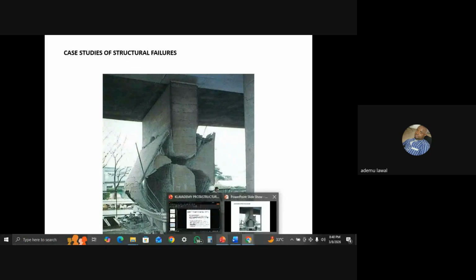Then you can do a support pier upward that can carry the load. But the first thing is you need to actually look at the design parameter of the failed buckled pier, so that you increase the load carrying capacity in terms of the size of reinforcement and the size of the pier itself, either by increasing the size of the pier or the size of the reinforcement, and then supporting it from the base again.